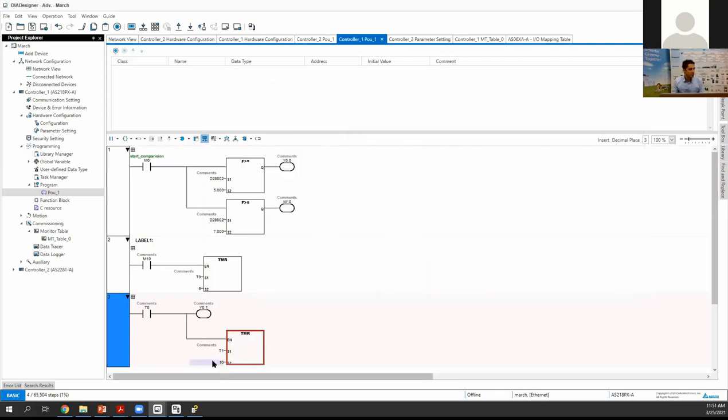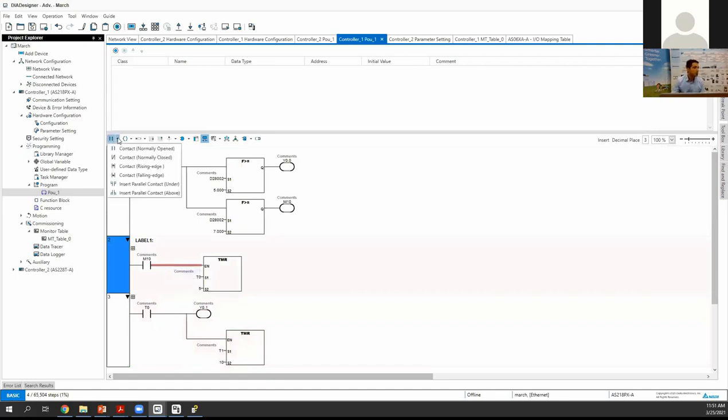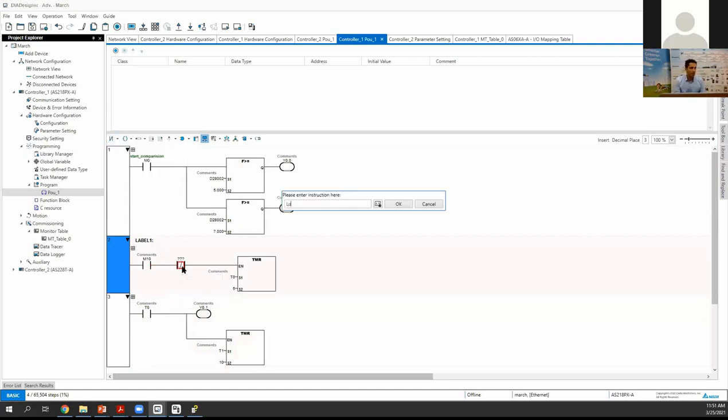So this is 1 second. So okay, this is on, timer start to count, reach to 5, then this is on and it starts to count, and when it is on, we need to initialize this. So how can we initialize? Simply we can put the normally closed contact, okay, and the shortcut for normal contact is LDI, okay.